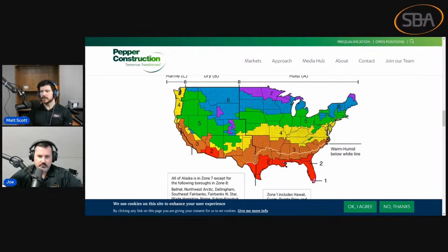And so you can change the conditions of what your heat load's going to look like. You can change the time of year you're designing towards. A lot of times we would look at that and try to design to like 70, 80%. But again, the difficulty of that is what happens when it does get to that hottest day and you can't cool it and your system's undersized. As I talked about, it really comes down to making sure you have enough redundancy and being able to hit those loads if needed. But most of the time, having a load that's satisfying at the 70%, 80% mark.